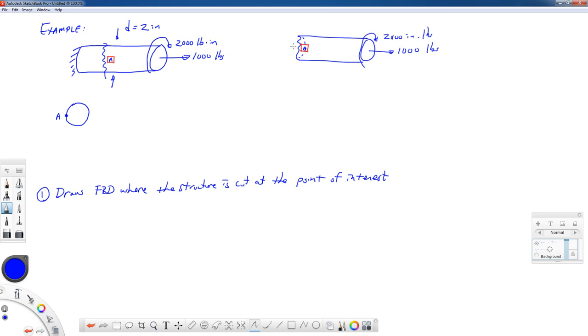that in order to keep this in equilibrium, we need an equal and opposite axial force of 1,000 pounds this way, and we need an equal and opposite torque. Now, I said 3 forces and 3 moments. Well, the torque is just a moment, but it's about a long axis of a bar. So to keep this in equilibrium, the torque has to come around the backside this way.